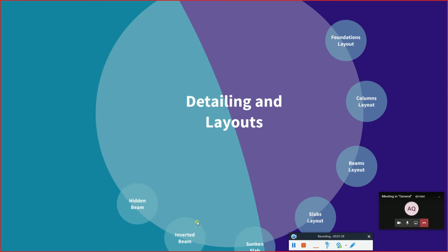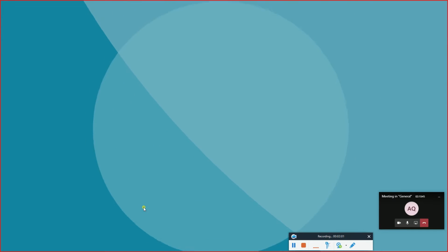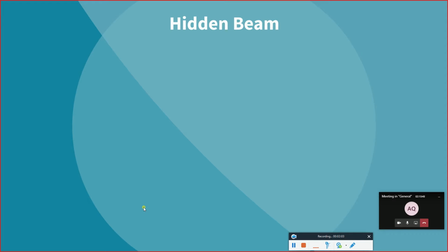Okay. So going for the first one, which is hidden beam. There are two names for this particular beam. Some people call it hidden beam, others call it concealed beam. It's already obvious from the name that this particular beam is hidden, meaning it cannot be seen like the other regular beams. Why can't I see it? Because it's inserted inside something. So it's available, but it cannot be seen by the regular person. Where is it hidden? It's hidden inside the slab.